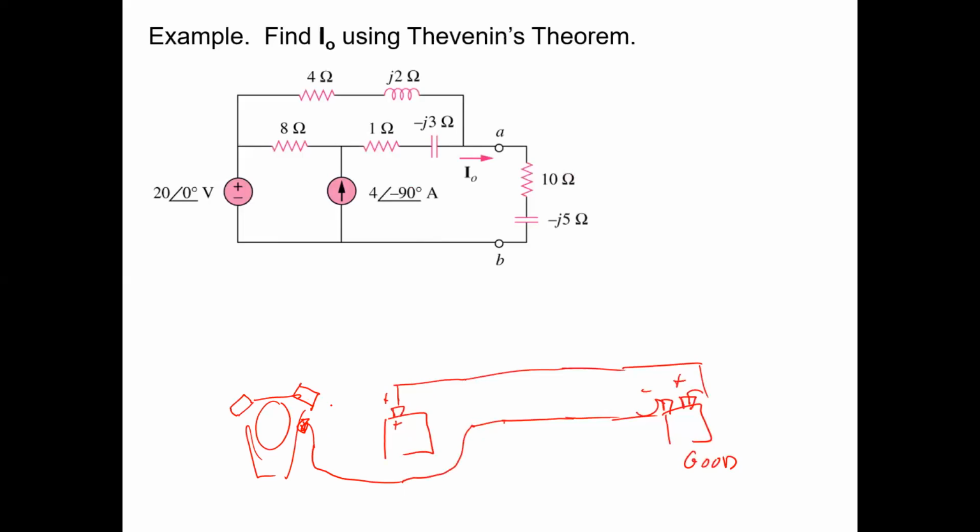Why do you do that? Well, I know a lot of batteries in cars have ground on the battery. Yeah, you could connect it there, but that would be unsafe. Generally, you want to make it away from the battery because when you make that connection, you could get a little spark.